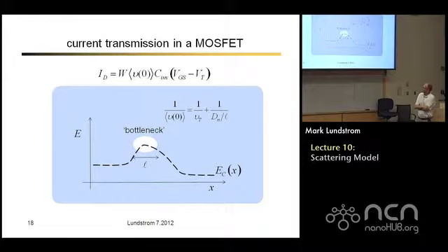You know, it's got units of velocity. D is centimeters squared per second, right? L is centimeters, so it's got units of velocity. You can think of it as the average velocity that carriers are diffusing. When carriers diffuse across a region of thickness x, their average velocity is D over x. So that's the average velocity of carriers that are diffusing across that regime.